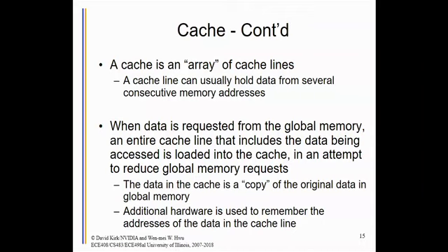put that into the constant memory cache, and use a hardware tag mechanism to remember that these bytes correspond to the memory address so-and-so, that's where the memory burst came from. And I have all the bytes in that burst, okay?